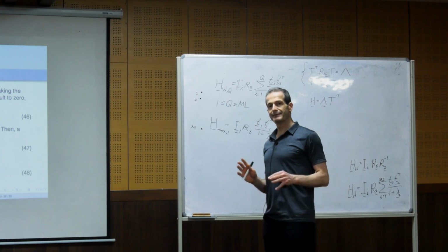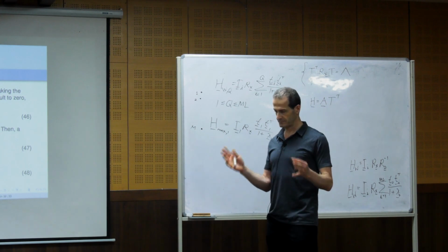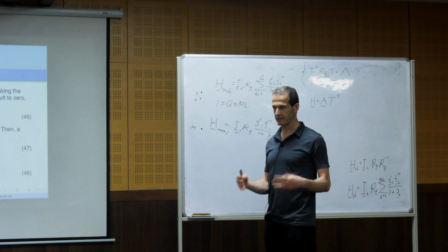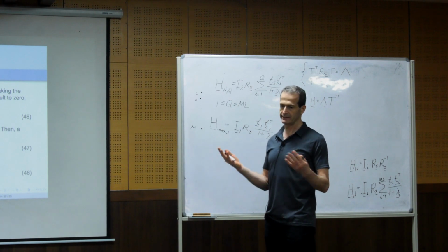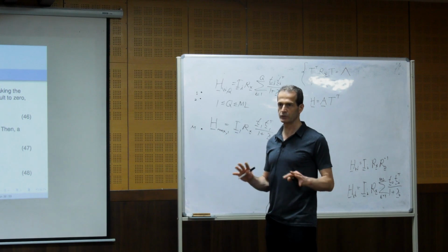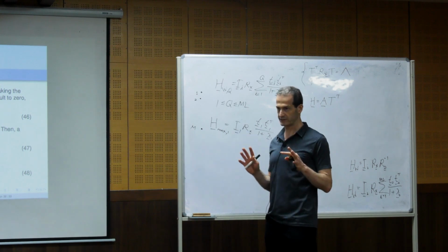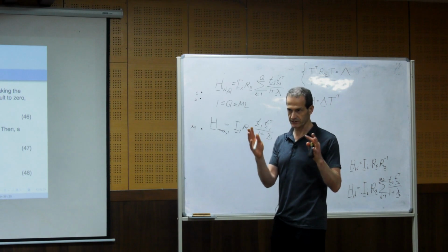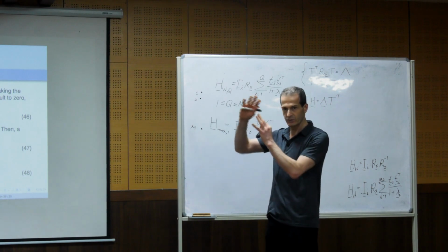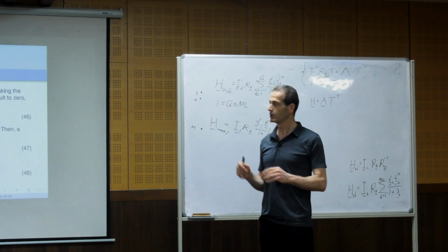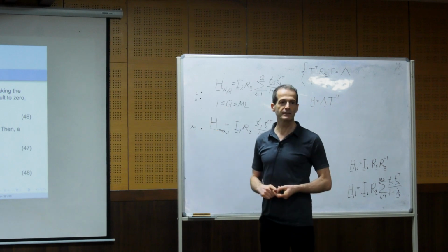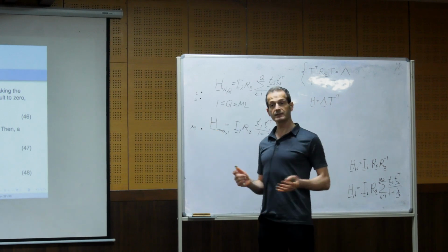So if we keep these eigenvectors, the projection on this signal subspace, we don't touch it. We don't reduce any noise in the signal plus noise subspace. We remove only the noise in the noise-only subspace. We get MVDR. It's very nice.